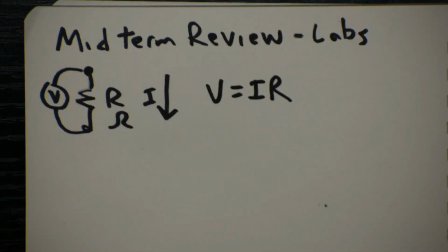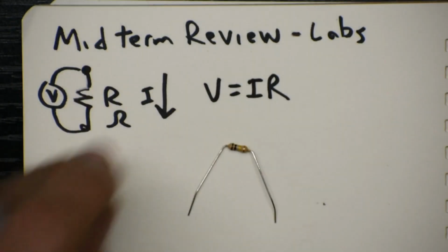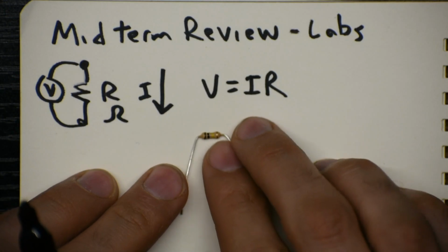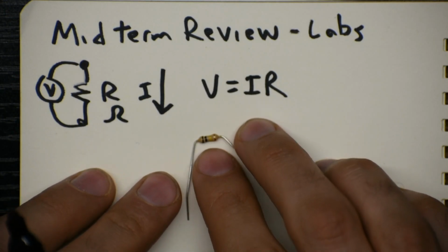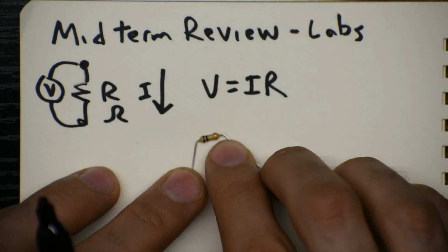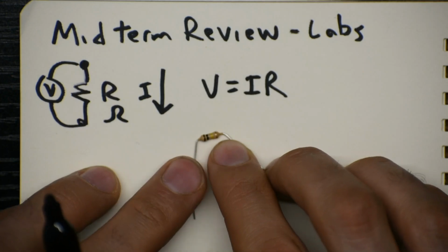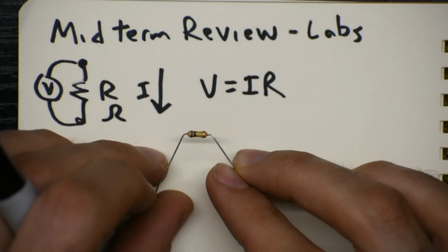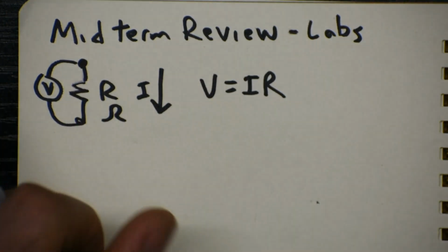Those are fun. Let's see if I can take out a resistor. Here's a 1/4 watt resistor. This is brown, black, yellow, gold. So this is a 100K resistor. The gold means that this is plus or minus 5% over its temperature range. I find that they're a lot better than that. And a 1/4 watt means that it can dissipate a 1/4 watt before it smokes.